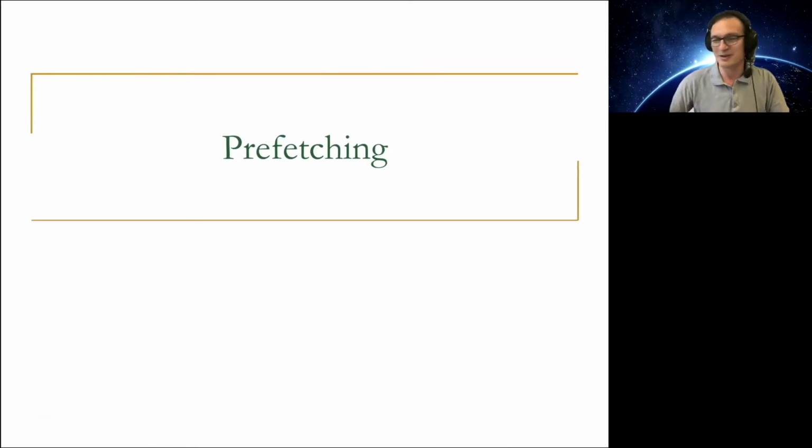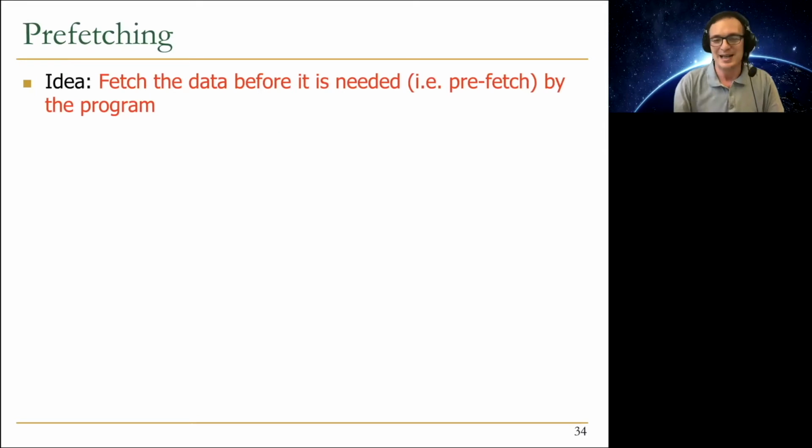Okay, so with that backdrop, let's go into prefetching in a little bit more detail, so that at least I can give you the basic ideas, and you know this important topic that's been keeping many people busy in the world. And the idea, as I said, is very simple. You fetch the data before it's needed by the program. That's why it's called prefetch or preload. Prefetch is more commonly used term today, but preloading is also used.